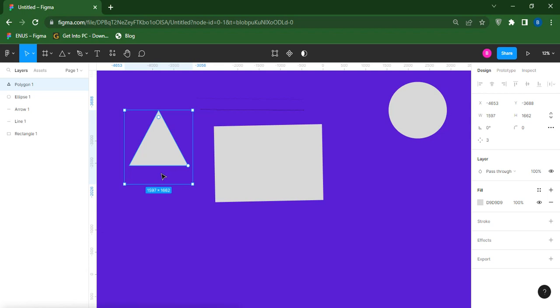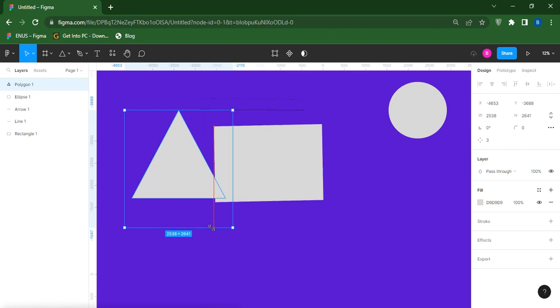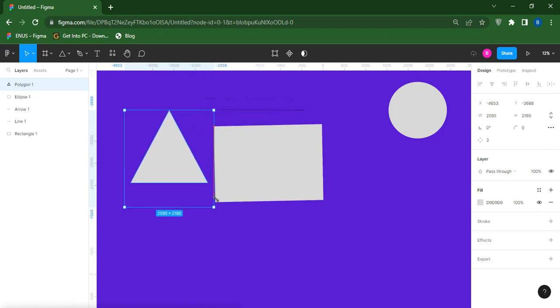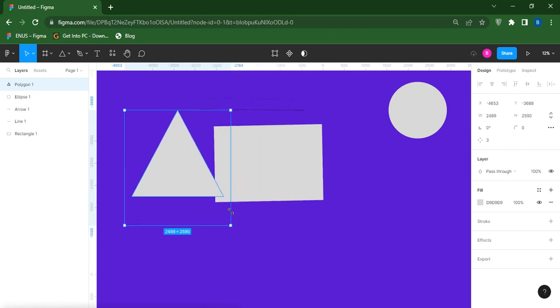and you want to resize and you don't want to press K or move to scale tool, you can just hold down your shift, then you left click and drag. You can see it's just as if it's in scale tool. You can see it will move and it will resize it without deforming the shape you are trying to resize.